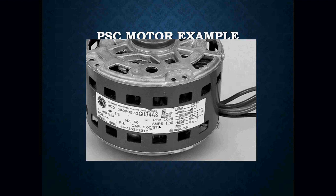It also gives you your rotation, voltage, hertz, horsepower, as well as RPMs, which is very good information to have, especially if you have a motor with a failed start winding or a failed run winding. So you can get a replacement motor with little problem.